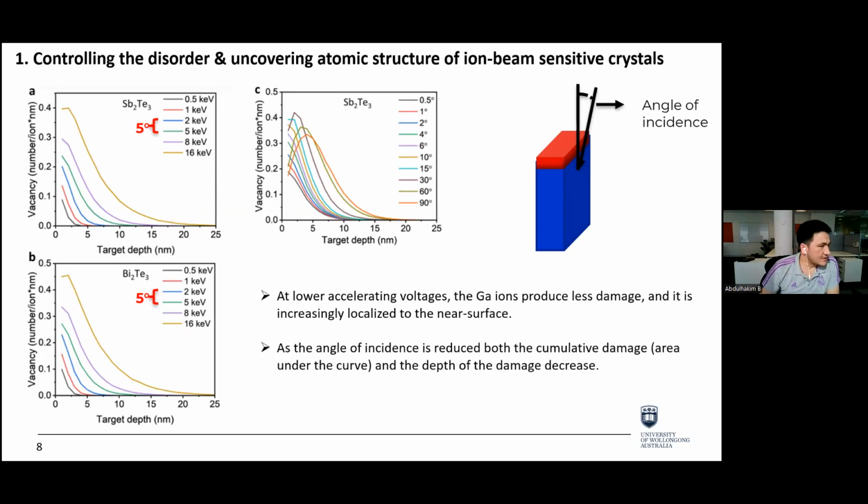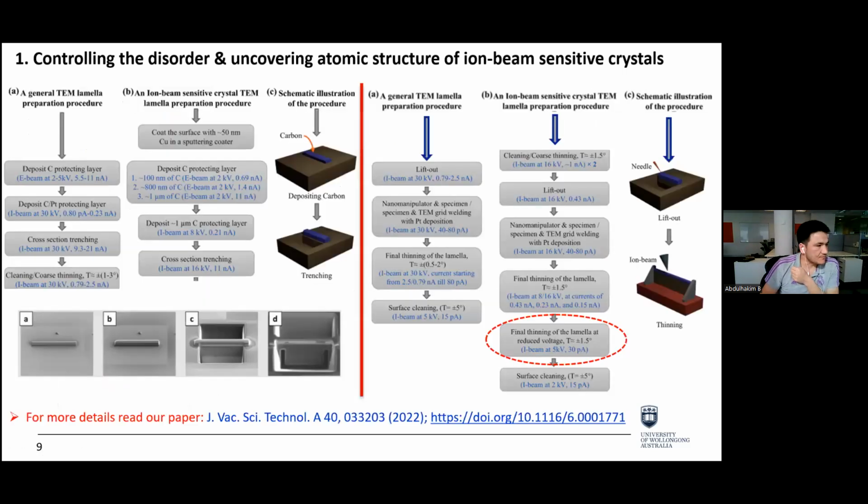As you can see, this amorphization or damage level depends upon the incident angle and also the energy. So by choosing proper energies, we can really fabricate high quality TEM lamella, where we can study the atomic structure of this material.